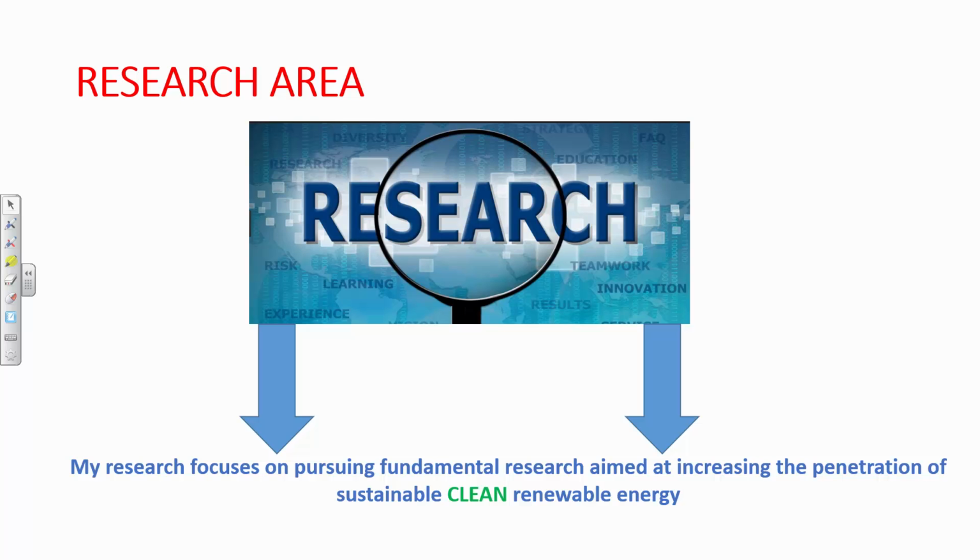The problem with renewables is that they are variable. If I have a solar panel on top of this building, during the night it doesn't produce any power because there is no sun. If I am relying 100% on that PV solar to power this building, I need to find another solution so that during the night I still have power supply to this building. So I need, for example, energy storage. During the day I can store some energy, and during the night, when the PV solar doesn't produce any power because there is no sun, I can discharge power from the battery and power that building. Now that battery comes with additional cost. So what's the optimal size for that battery? And at larger scale, utilities need to build a huge battery storage system, and that comes with additional cost.